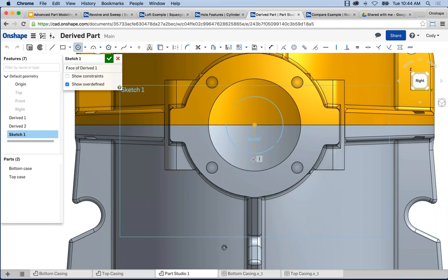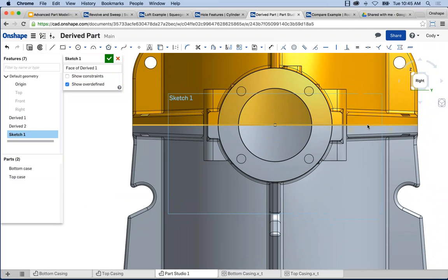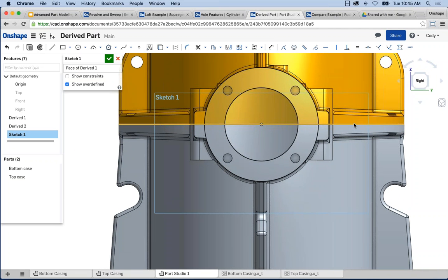So now I can use the imported model to attach my sketch geometry. Right? And so it makes it very easy to work around existing models. Now I'm using this example of working around existing models, but this works the same way if you like to use layout sketches, for example. If I like to create a single sketch that drives everything, I create one part with nothing but a sketch, and I use that one sketch to insert into other parts so that I have one master place to control everything. But now I can even do things like convert the existing edges.